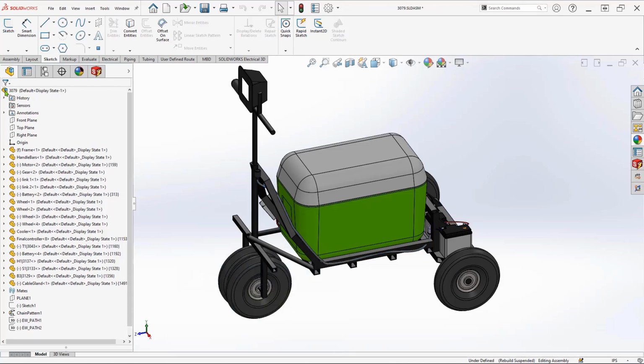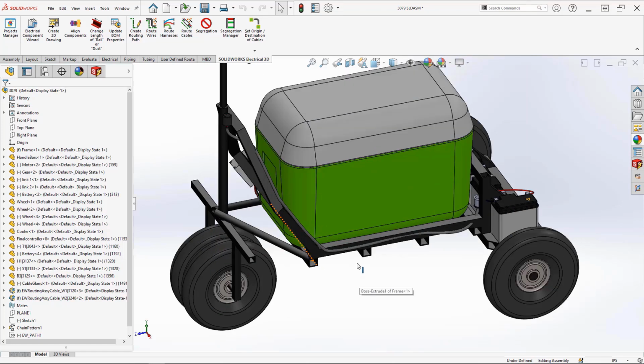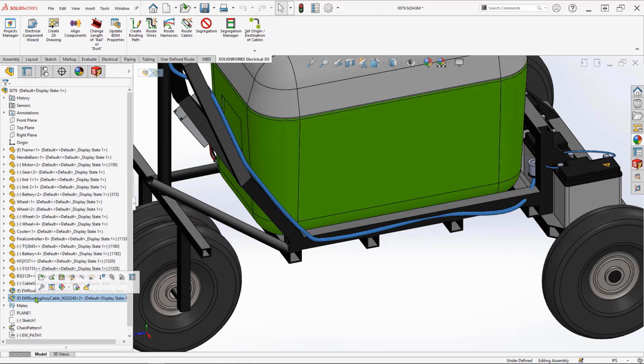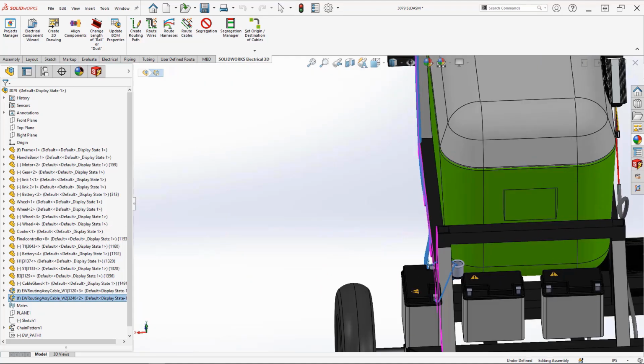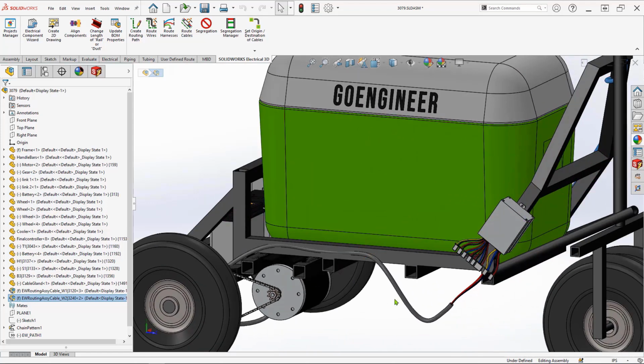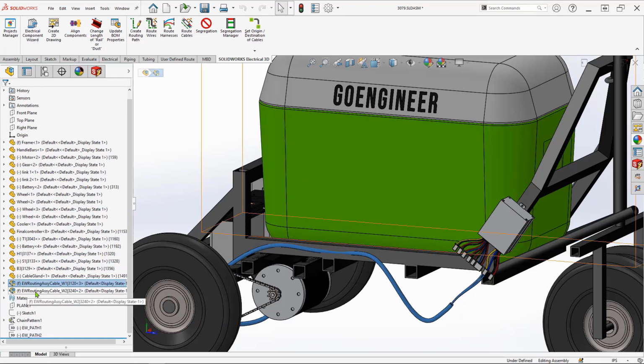You can see here, now we have one cable that's closer to us. We can select him here. So he's running along there on the edge of the frame. Oh yeah, it's that second cable, and it's connecting to the battery. So it's going from a switch up to that battery, going through a cable gland, kind of oversized. And you can see here, that's our other cable that's following that spline path. So that's pretty cool. So you can have separate cable assemblies inside of SOLIDWORKS Electrical 2021.